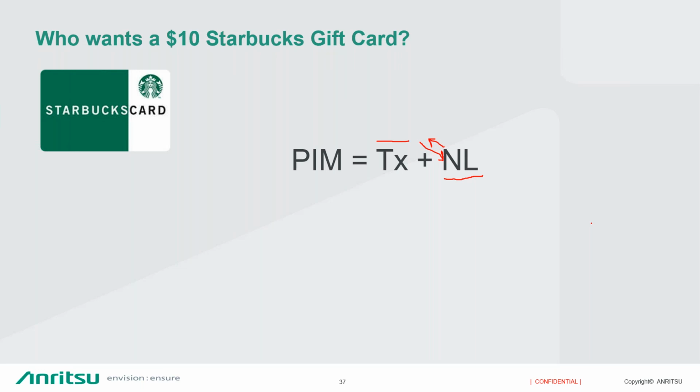Okay, we have just a couple more. For external PIM hunting, do you need a band pass filter? For external PIM hunting, yes. If you're doing a troubleshoot, and it sounds like maybe I'll do a second webinar on the actual troubleshooting, you do need a very precise tone and a very precise spectrum analyzer that's calibrated to that certain IM product's frequency so that you can find the exact location of the nonlinearity. Hopefully that answers the question.